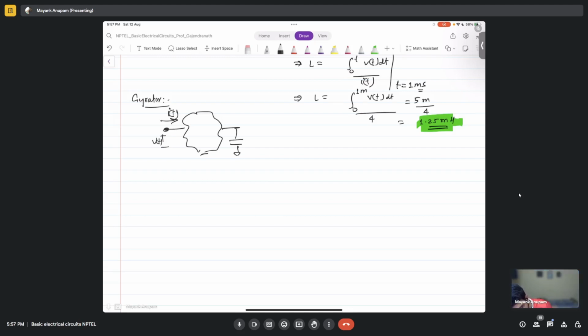You're getting what I'm trying to say? From this side when you look, it will feel like an inductor, but here it is a capacitor, and you will not place any inductor in this network. You will place some elements here which will make us believe that the capacitor is looking like an inductor when seen from this side.